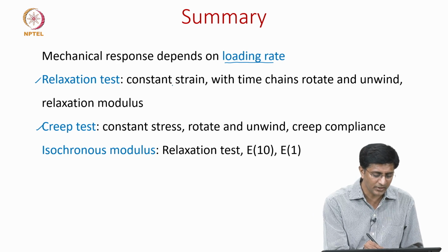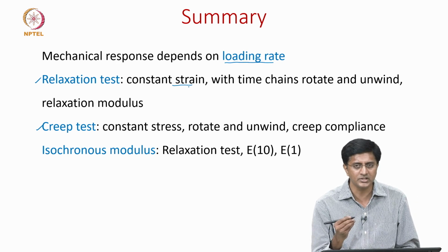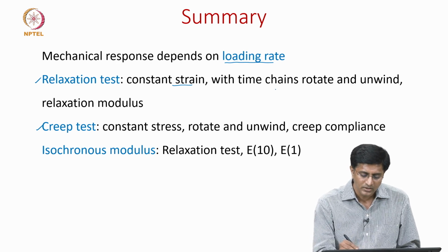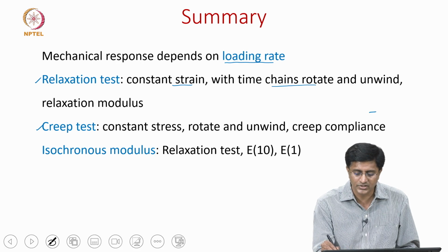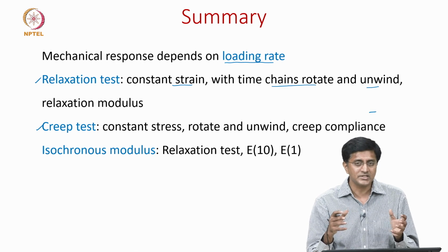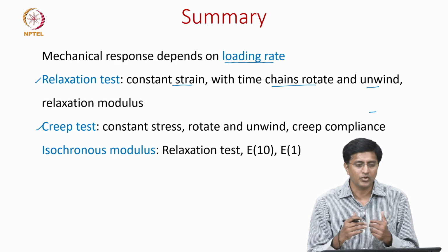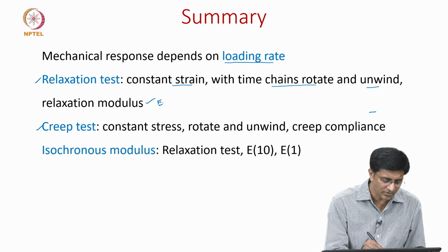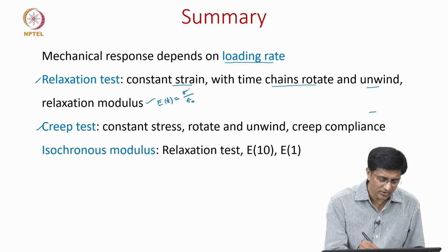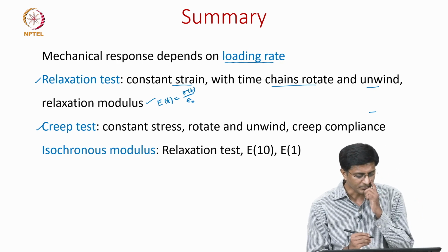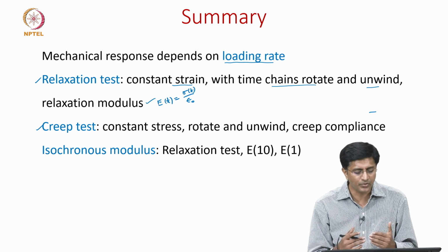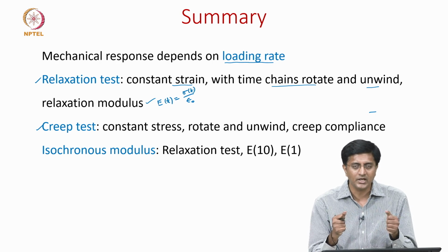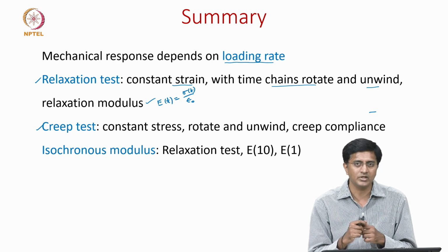In relaxation the input is the constant strain and we measure the stresses. We have seen that because of the rotation and unwinding of the chains, the stresses reduce given more time. And we also discussed the relaxation modulus, which is a function of time and is given by stress by strain. Strain is constant and stress is a function of time. Similarly, for creep we said that we apply a constant stress and measure the strain as a function of time.